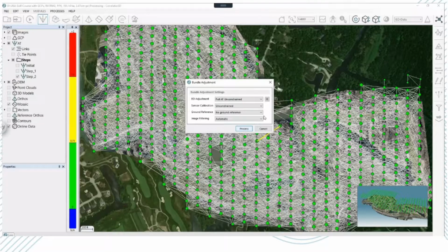But we get into the questions of what is the constraint method? Like what can actually constrain? And this jumps into the EOs and the IMU and the type of sensor that you have. Are you trusting the EO file that you have? It goes back to also the RTK method where you might not be allowing the software to do any movement on the images because you're trusting what's coming out of that sensor, out of the IMU.